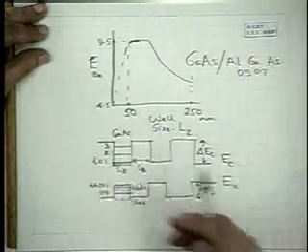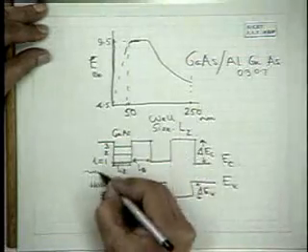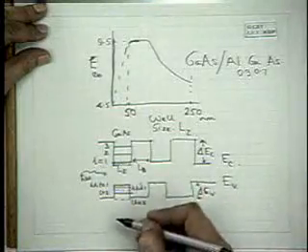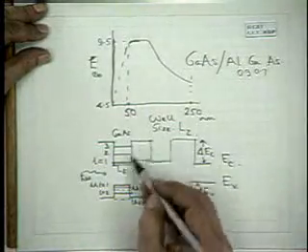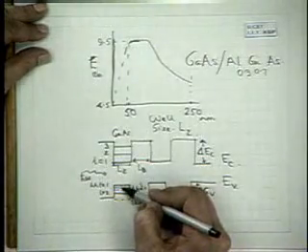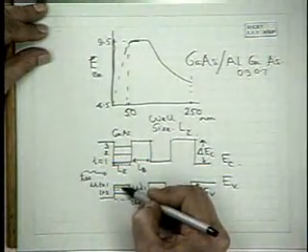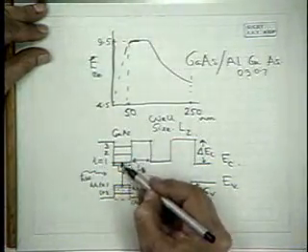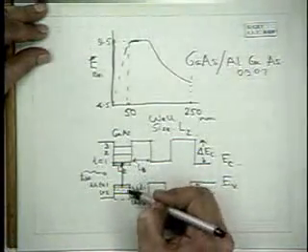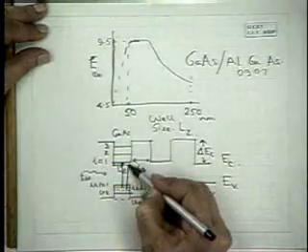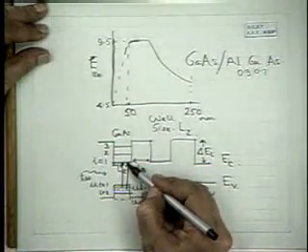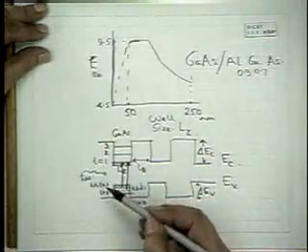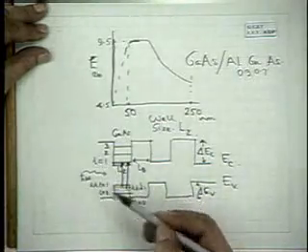So when light is incident on such a quantum well, we can get excitations from the heavy hole band. The first excitation, the lowest energy, will be from the HH L equal to 1 band to the electron L equal to 1 band. Then the next one will be from the LH equal to 1 to the electron L equal to 1. There are selection rules that say that delta N equal to 0 will give you the strongest permitted absorption.